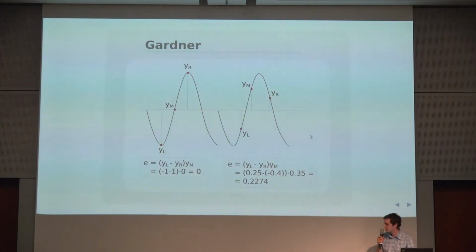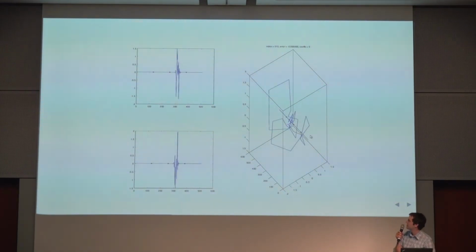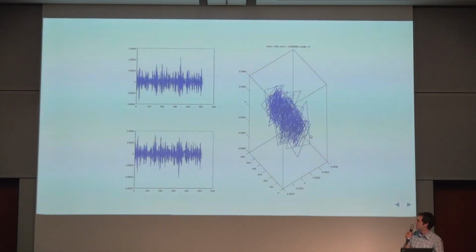So the other algorithm is the Gardner that I implemented, and there is the formula for it below the graph, and it tries to move the left and the right dot at the top of the symbols, so at the maximum power point, and this is how it is visualized with CSDR and GNU Octave.